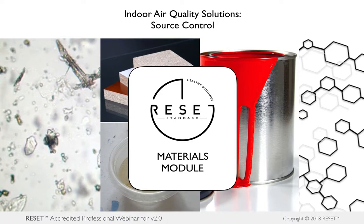Every product, every finish, every material has to be researched and reviewed and cross-checked against a prescribed set of criteria. And if you've done the material vetting for a project before, you know how difficult this can be, gathering complete disclosure of chemical ingredients, all that information, as well as information on VOCs and off-gassing. And further, it's ideal if you can get this information verified by a third party. And this is just not an easy ask. It's demanding and time consuming.